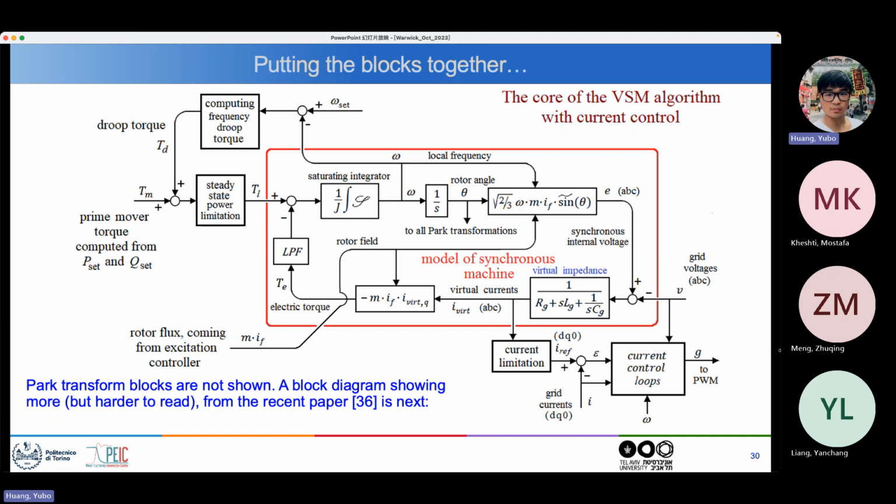Why? Because here we are dealing with measurements. You don't have real voltages. You have measurements, and you have PWM signals which all have tiny errors and biases. These tiny errors and biases might create a tiny constant bias of your output voltages. And because the output impedance at frequency 0 is very low, because the inductor has 0 impedance at 0 frequency, a tiny error in your output voltage could create a huge DC current.